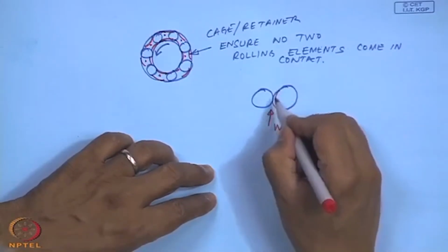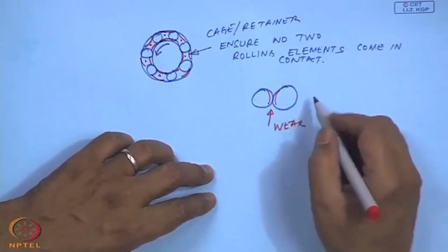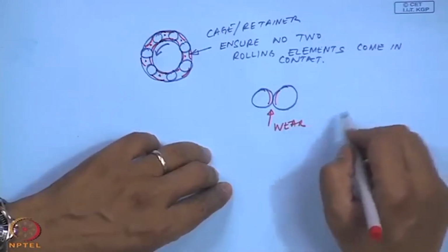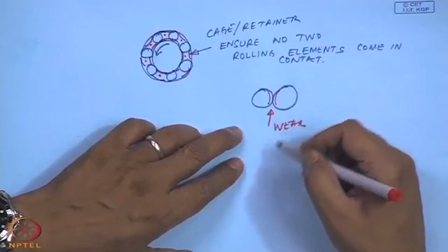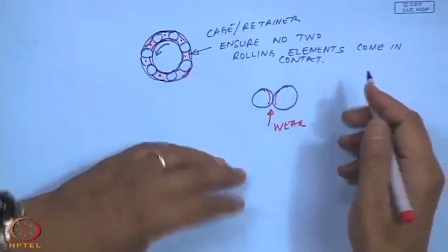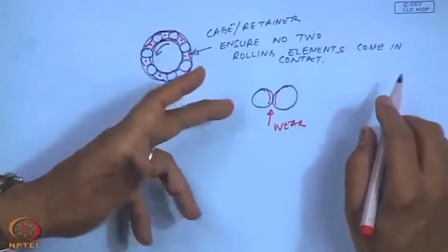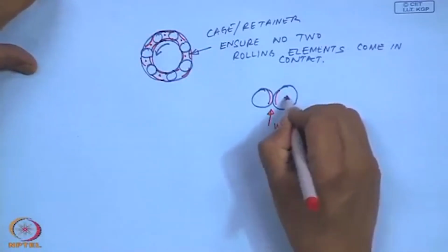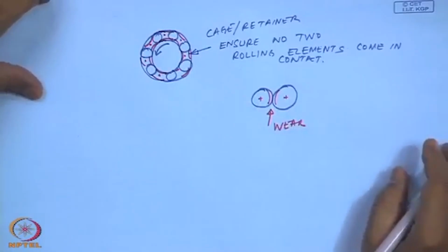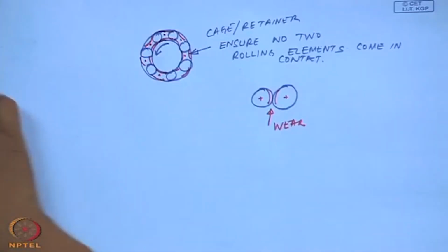They will get deformed, okay, and then they will not be perfectly round, and then they will have more friction, and then more noise, more vibration. And that is what we are coming to, the next topic about rubs. Okay. And if these things are rotating, we should avoid this, coming back to rubs.